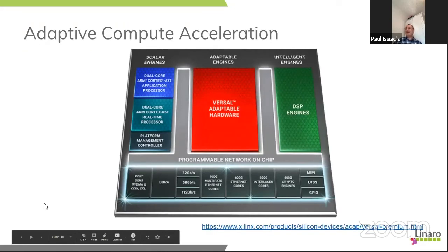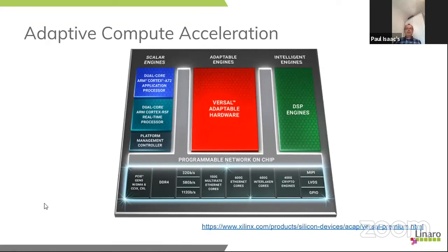No problem. So the alternative is we go FPGA in the accelerations, and here's an example from Xilinx, which matches a Cortex-A72 core with the possibility to add FPGA solutions. It supports CCIX and CXL, it's got Ethernet, but the A72, just going back to the ISA architecture, is actually version 8.0. So you would have to implement in FPGA any extended commands. Next slide.